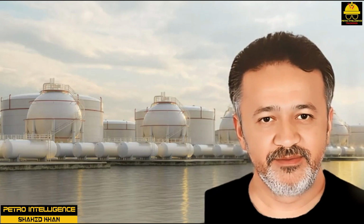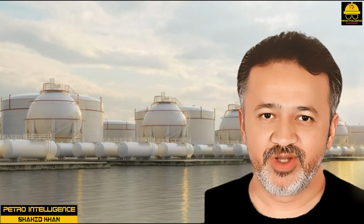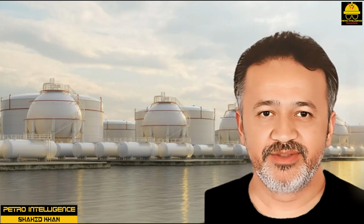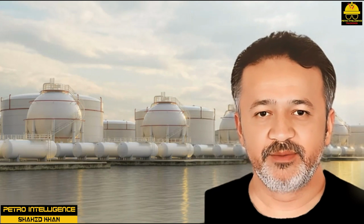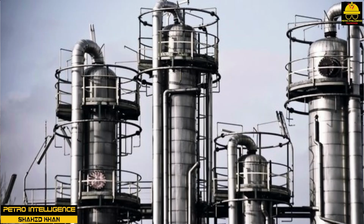Aluminum alloys. The outstanding characteristics of aluminum are its good resistance to corrosion from sulfur compounds and its resistance to continuous oxidation when exposed to the atmosphere. Because of its resistance to corrosion by sulfur, aluminum is used for internal parts of equipment processing high-sulfur stocks. It is often used in sheet form to protect and weatherproof insulation on pipe and towers because of its resistance to atmospheric corrosion.